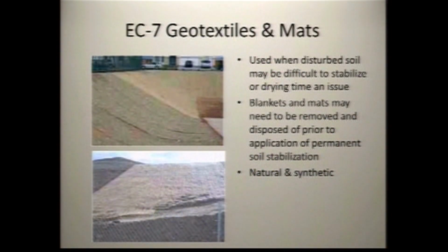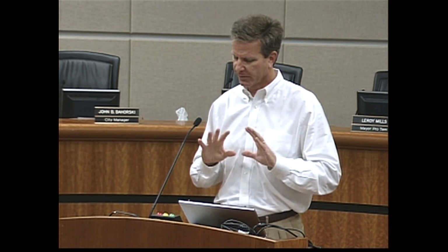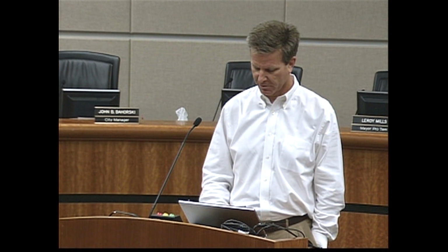And then lastly, in terms of erosion control, a very expensive option, but a good performer, are geotextiles, mats, rolled erosion control products. These need to go down on an absolutely smooth surface. If the surface isn't smooth, they're going to be up off the surface, and they're not going to work, because the way they work is by slowing the water down at that soil mat interface. So if they're put in correctly, they work very well. These are usually for pretty small areas that you just aren't planning on landscaping, because they are pretty expensive, but again, a good performer.